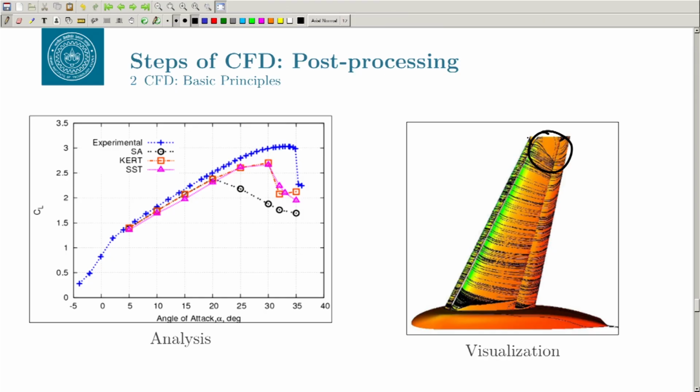geometry creation, grid generation, solver setup, simulation, and then post processing. I went through all these processes, and whenever you do any CFD simulation, you also have to go through all these CFD processes. We went through one example, but you can take any flow example, or when you read any paper, you would see they show you a grid, computational domain, boundary conditions, what convergence level they are using, what turbulence model they are using, and so on, and finally they will show you the simulation.